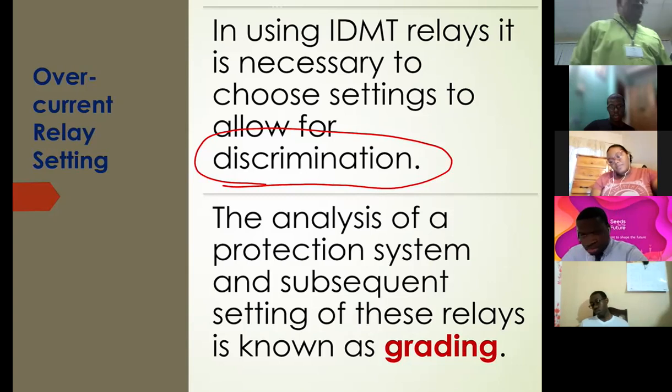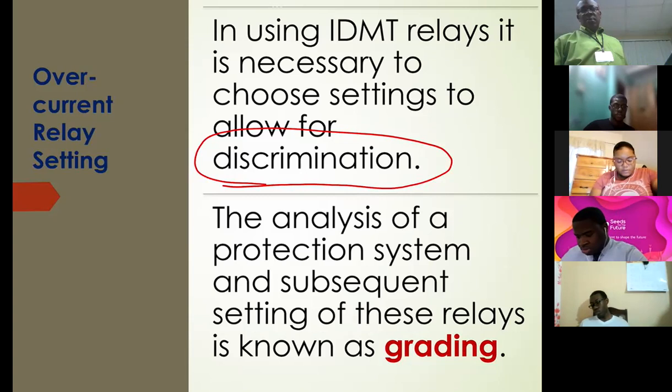And that activity that we are going to get into is known as grading. So we're going to look at a grading exercise. How do I go about setting some relays to ensure that I get the discrimination?